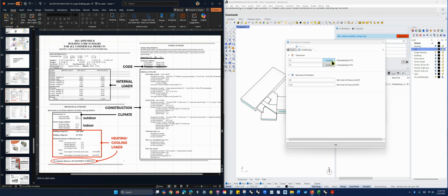Okay, but then we could also set a schedule if we wanted to. Now, the temperature set point should turn the heating on and off when we get to those temperatures. So in a way, we don't necessarily need a schedule, but there are schedules that change the set points. So like they say, okay, well, at night, if it's winter, we can let it go down to 65 degrees, or there are other things that a schedule will adjust.